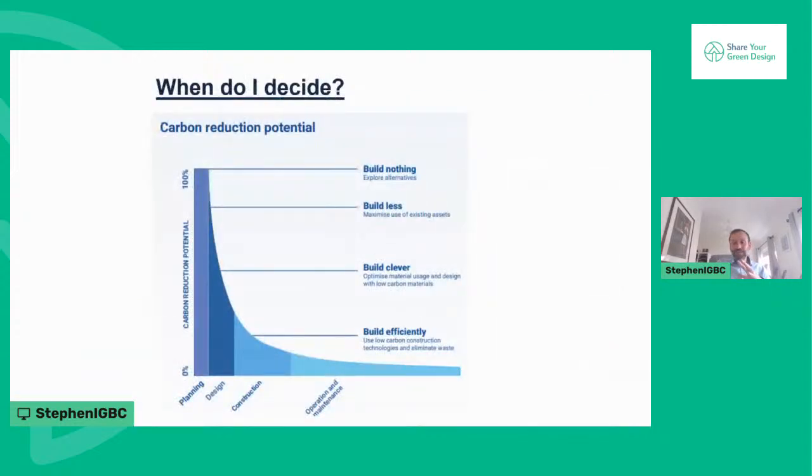So finally, when do you do it? As early as possible before anything is locked in. The lowest carbon building is no building at all. So the first thing to do should be to look at other possibilities. Can you repurpose an existing building or renovate an old one? What existing assets are available to you, and can you make them suitable? A renovation will almost always have lower embodied carbon than a new build, as you avoid the need to produce new foundations and structures, two of the largest contributors of that upfront carbon.